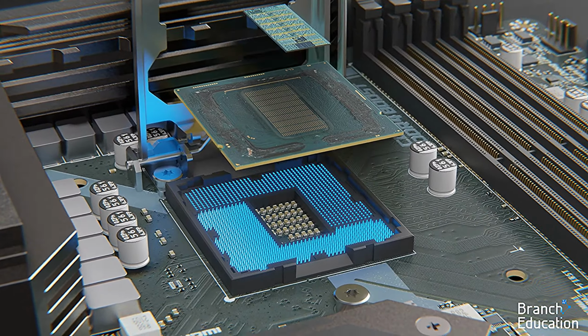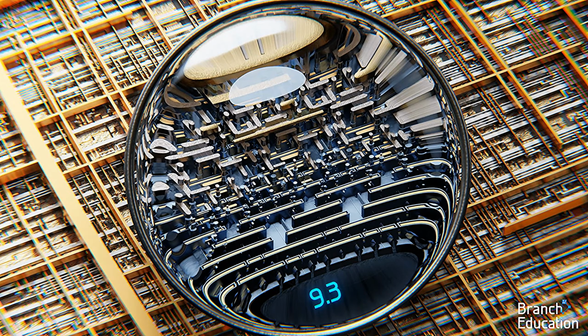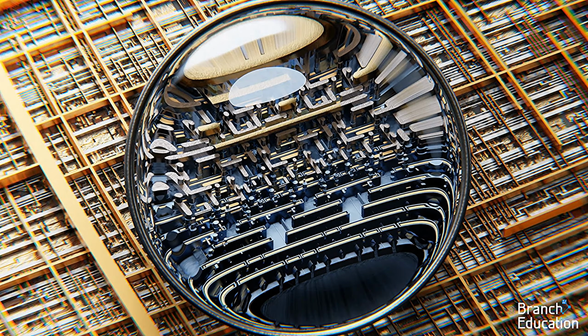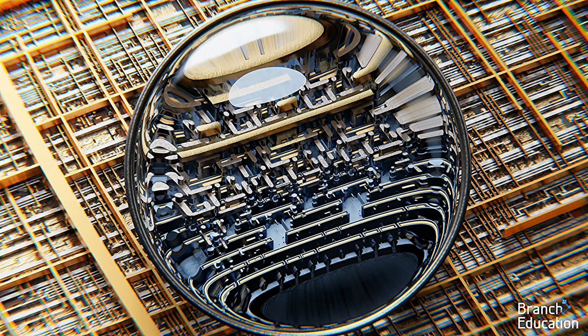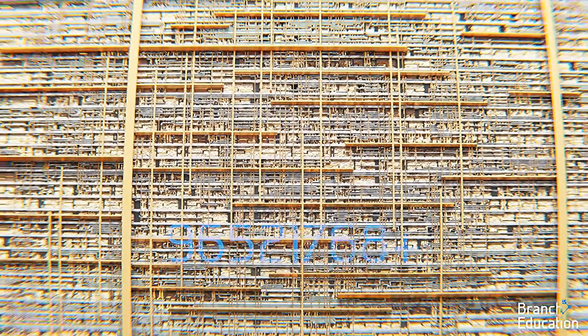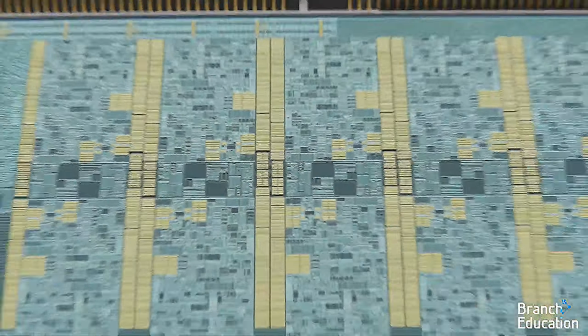Let's zoom into a nanoscopic view of the integrated circuit so we can see individual transistors. These transistors are incredibly small, only a few nanometers wide, and in this die there are approximately 8 to 10 billion. On top of the transistors are multiple layers of metal wires, with vias rising vertically between the layers. Together, these transistors and wires create a multi-layer labyrinth or highway, resulting in a computer that can execute billions of operations every second. Let's now zoom out and look at other sections of the CPU.